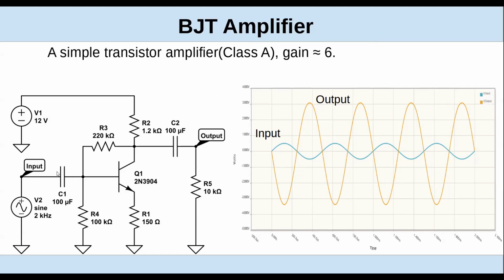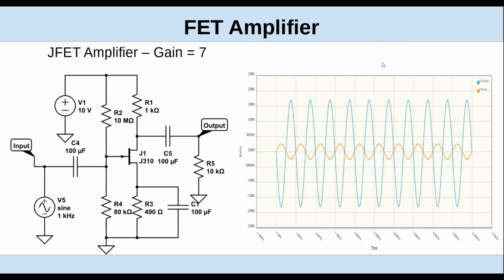But in this circuit, basically, you're using the R2, R3, and R4 network to establish the bias point, which is about in the middle, which would be around 6 volts. And you normally use a little emitter resistor that helps stabilize it. It does an offset voltage. That's a pretty standard configuration. It's one of the things I learned in college decades and decades ago.